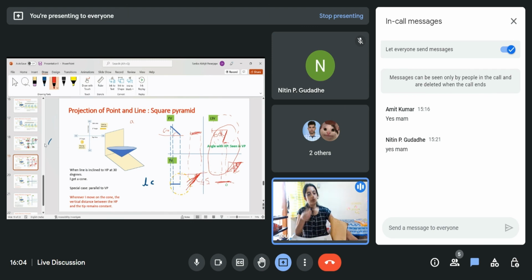So when you are given problems, how will you be given? They'll say the apparent angle. So see, like I said here, here I have rotated by 60. So after rotation, this does not remain 45. It will be more than 45, let's say 55 degrees. After rotation, the apparent angle with respect to VP looks like 45. But is it the actual angle? I did not change the angle with VP. It is 45 only. I just rotated it like this. So in that case, you need to imagine all these things so that you don't get confused.